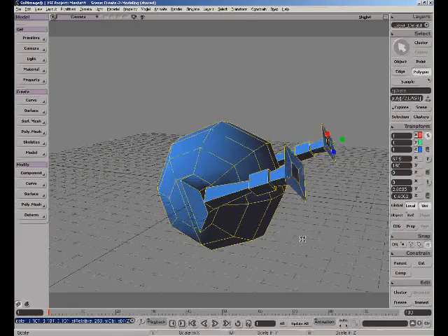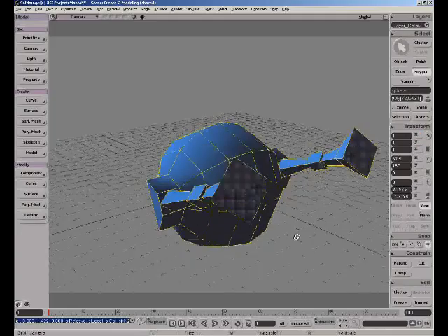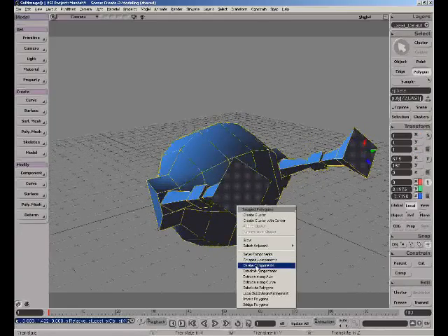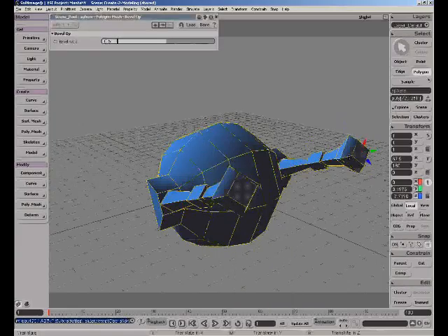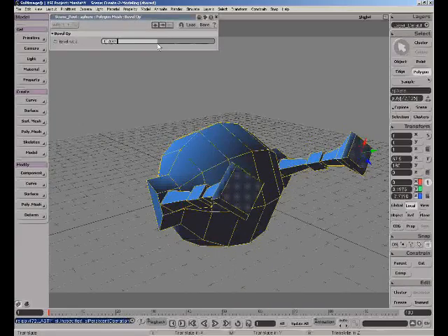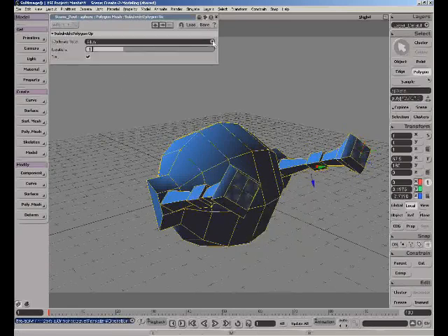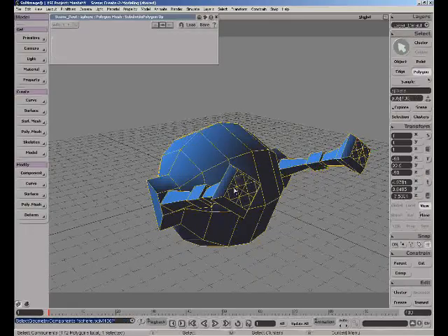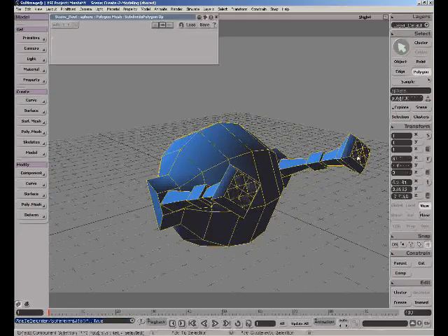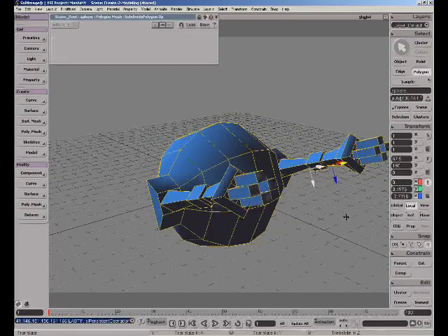And let's go ahead and do another tool. We'll use the bevel tool, pull this like so, and right click and just say bevel these components. So you get a nice looking bevel here. Here we can use the slider to control the amount of bevel that we're getting. And lastly, one more tool, we'll subdivide these again, and add the diamond shape, increase the level there. Just go ahead and select these like so, duplicate them, and pull them out.